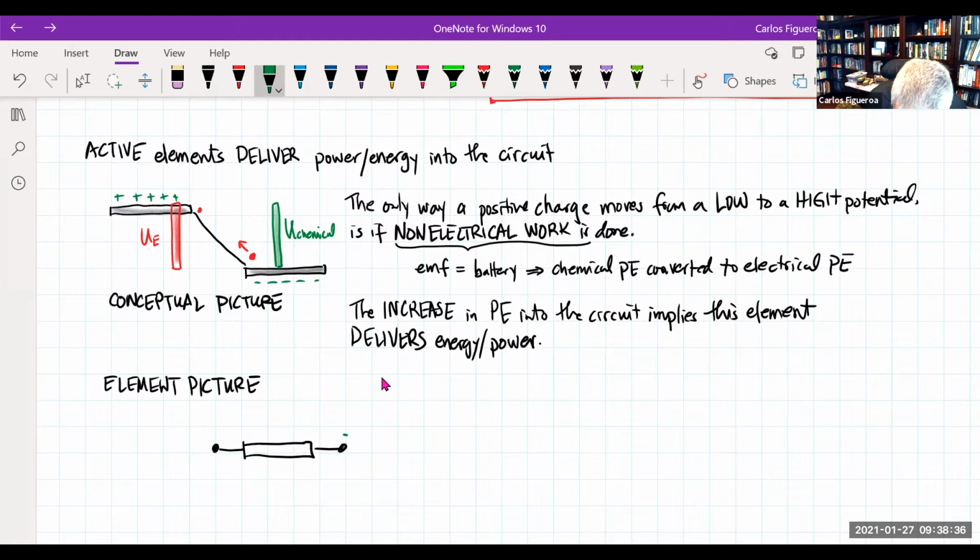So one end of the terminal in this case is negative, the other one is positive. When I'm looking at this element right here, look at the current, it's going up the negative. So it's going from the negative in this direction. What you're seeing here is that the voltage across here is positive, but the current's entering the negative terminal. So this is a different sign convention. That means in this case the voltage is positive, but the current this time is negative.